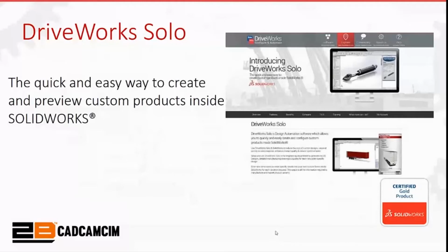We create a master model, we put in it all the needed info, and then we select from this master model the dimensions, the features, the components we want to be derived in other scenarios. We build a form to insert the inputs in, and we define the rules that will control these variants. This is as simple as it is.